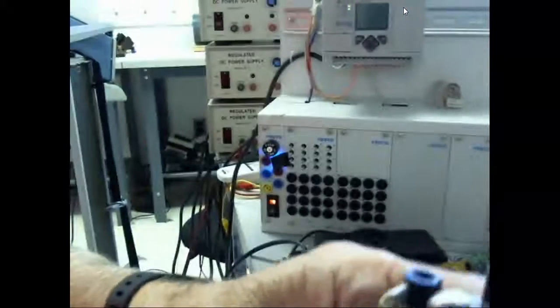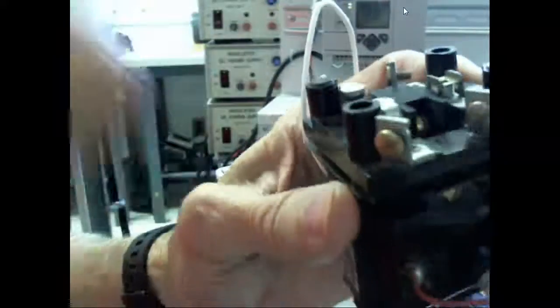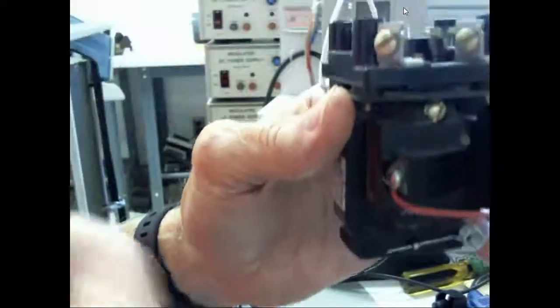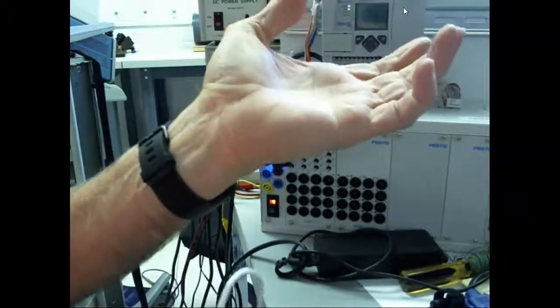So a relay is an electrically controlled switch, right? So this would be double pole. Why would it be double pole? Because I got two sets of contacts controlled by the same operator, and each one of them is only controlling one thing. And so these would be single pole. So just about all your relays are single pole anyway.